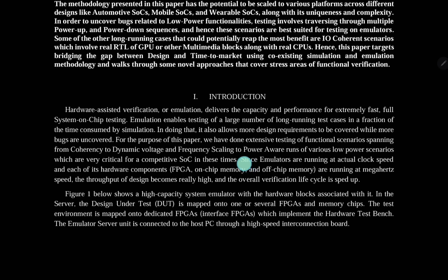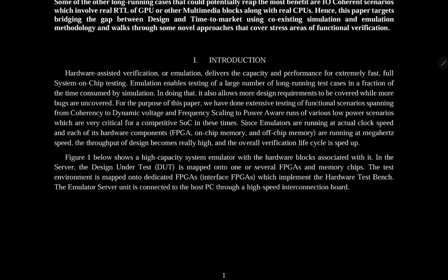SoCs at this time. Since the emulators are running at actual clock speed, and each hardware component, FPGA, on-chip memory and off-chip memory, is running at megahertz speed, the throughput of a design becomes really high and the overall verification life cycle is sped up.